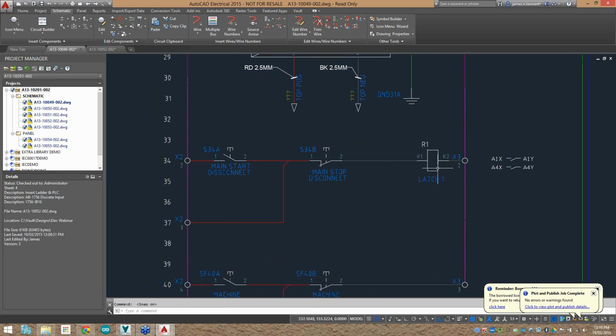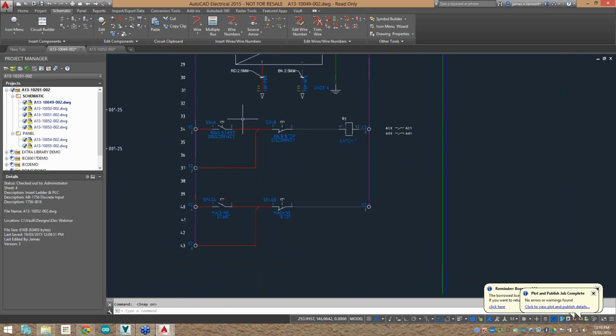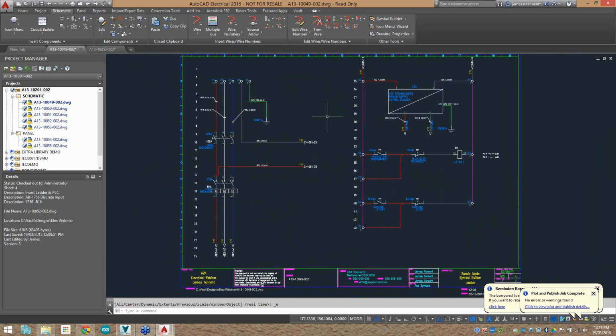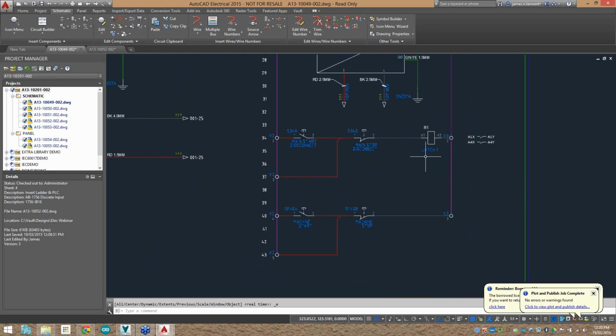One thing you will notice when I'm using AutoCAD Electrical is I am using snap or grid snap, which is probably what a lot of you are thinking is a little bit backwards, because in AutoCAD you're sort of taught to use OSnap and not grid snap anymore. But I find that grid snap is actually very useful in AutoCAD Electrical to make sure that all your wires are evenly spaced away from each other and those sort of things. So grid snap is a fairly useful tool in AutoCAD Electrical. And again, it would be something that I would set up as maybe 10 mil spacing between each grid snap.